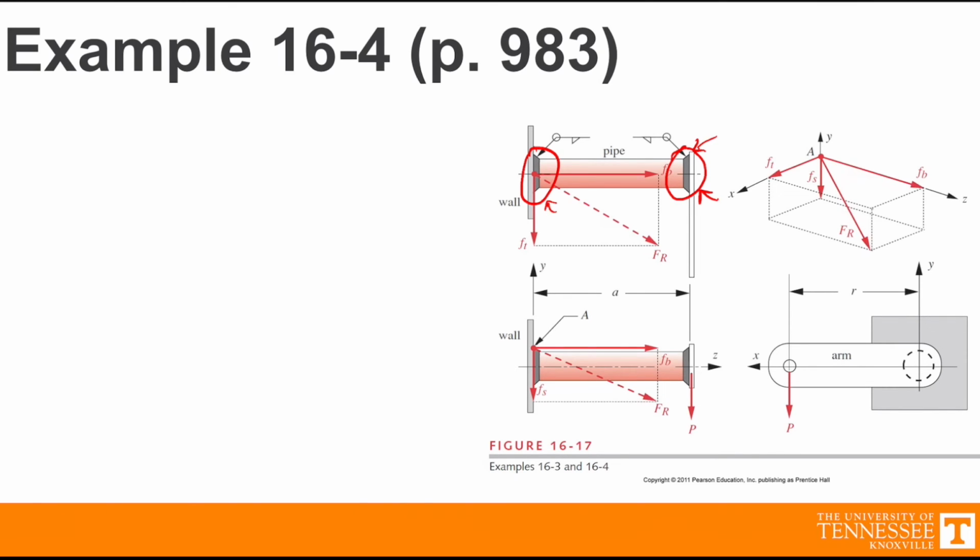So looking at this weld against the wall again, we need to determine, if we look back at our fillet weld, which looks something like this, if this section right here where the wall and the fillet weld meet is going to rupture. So we're going to use category C, and we're going to treat this as a more standard stress problem by finding the von Mises stress. So we're going to look at the two different stress states that are going to produce the stresses.